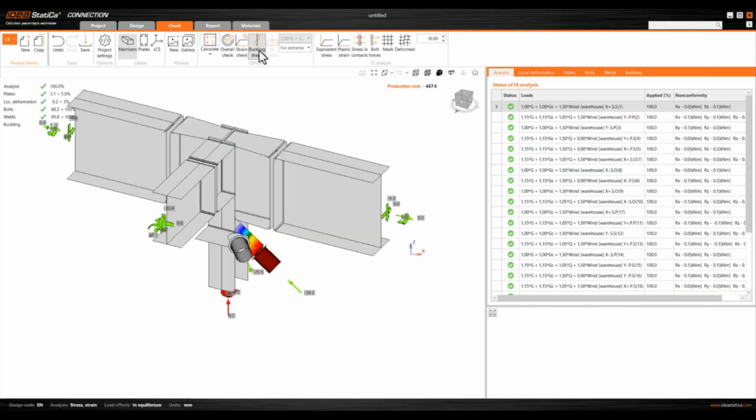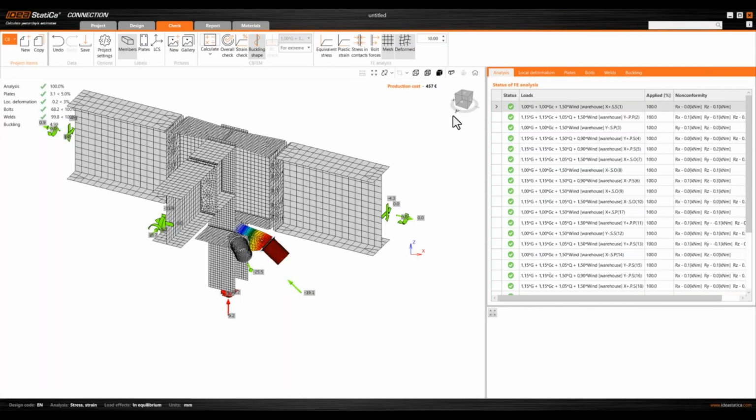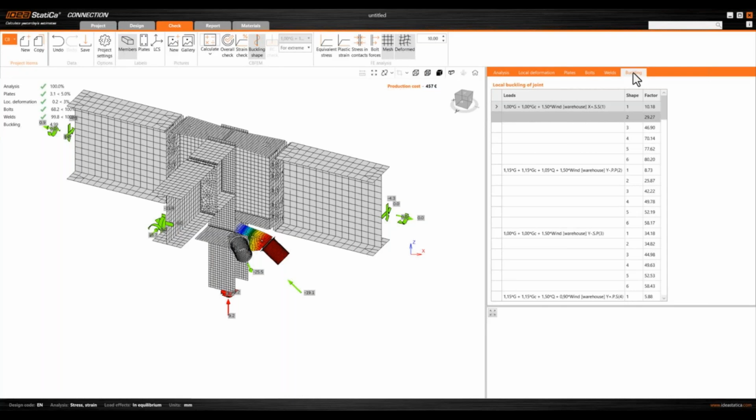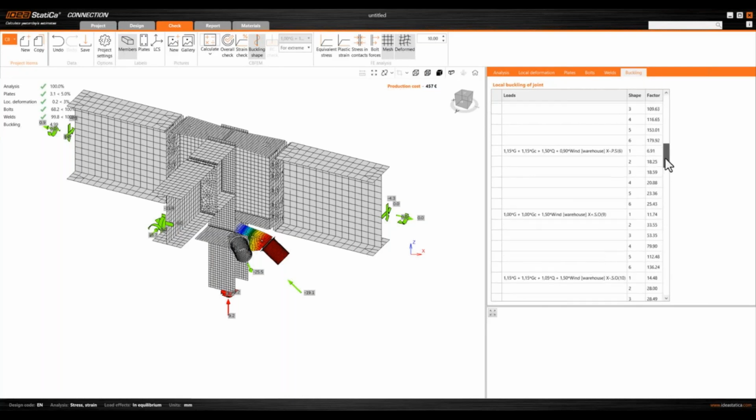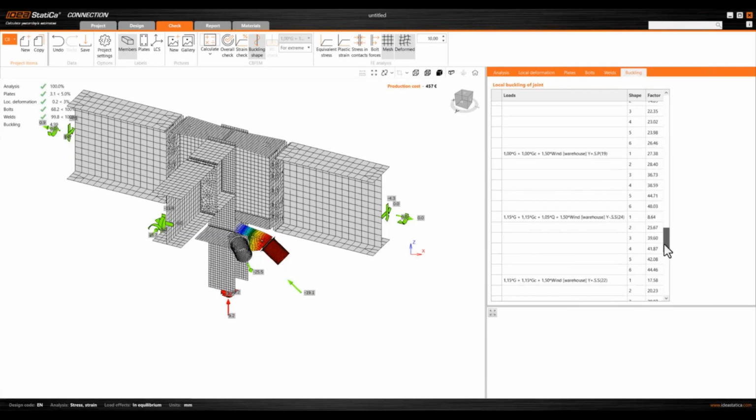This is clearly due to the vertical bracing gusset plate, which is this dangerous type of gusset that is connected on one side. This is the reason that it has a lower buckling value than the other end of the connection that is connected on two edges.